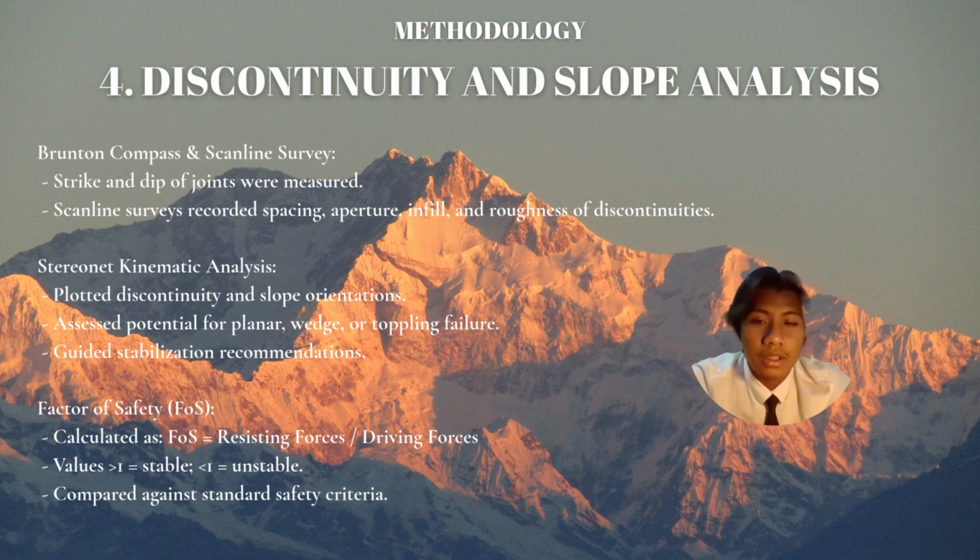So the last methodology is discontinuity and slope analysis. So the first one is Brunton compass and scanline surveys. The strike and dip of joints were measured, and scanline survey recorded spacing, aperture, infill, and roughness of discontinuities. So the second one is stereonet kinematic analysis. We plotted discontinuity and slope orientations, assessed potential for planar, wedge, and toppling failure, and guided